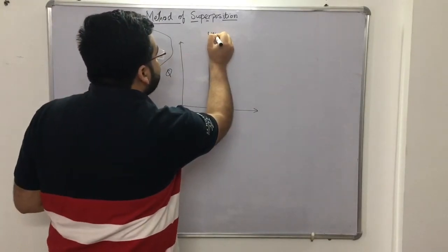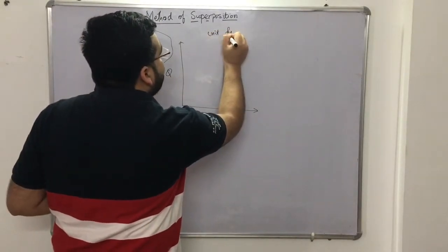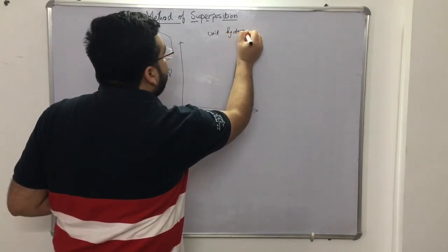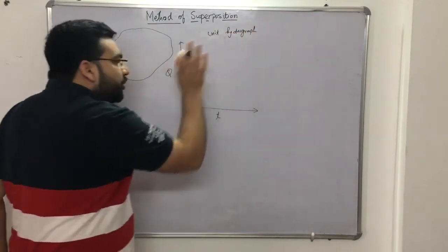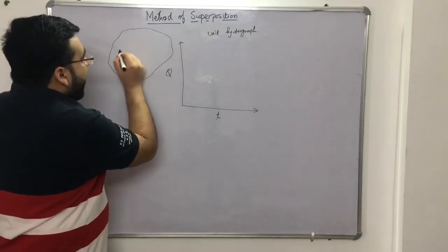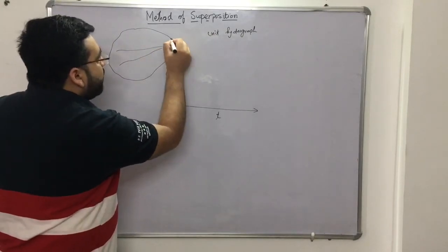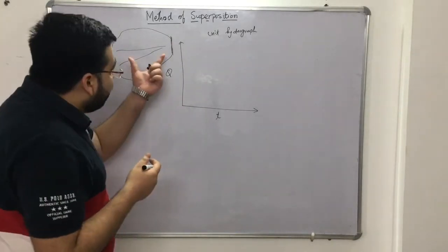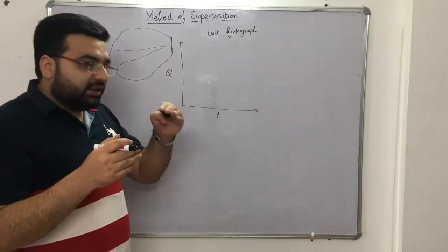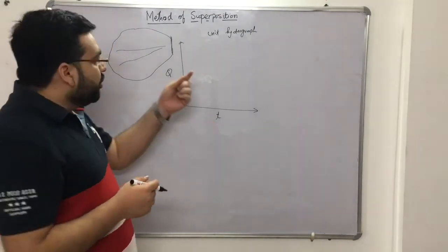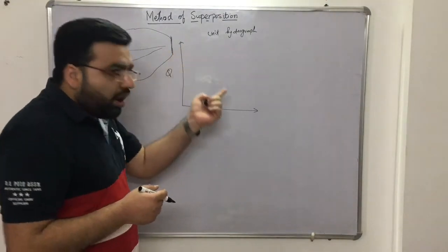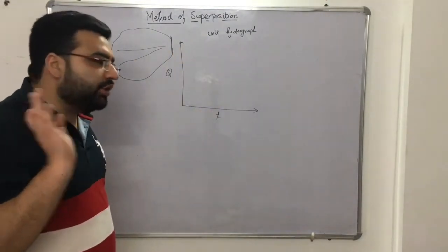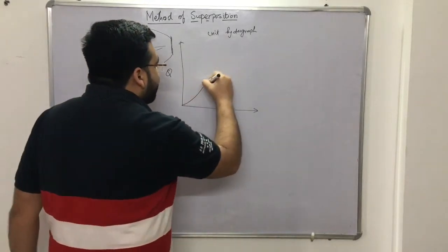How have you got the hydrograph? At the catchment outlet you have made a gauging station, and with the help of this gauging station you recorded the effective rainfall and the runoff, and hence you have got the unit hydrograph. So this is the unit hydrograph that you have got.